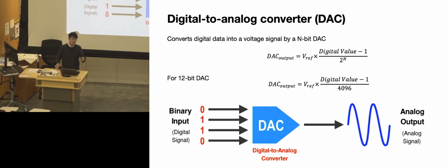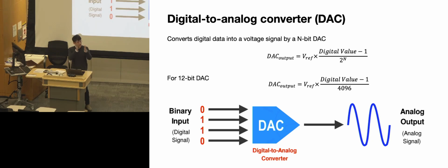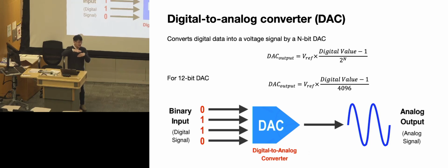That's a very good question. You could configure it as either everything run down, run up, or in the middle. I'm not sure if you remember in the last lecture, you could decide whether the 0 starts at 0 volt or starts at, say, the least significant bit, one step up. The essential reason for the -1 is that we have, say, n values, and there are only n minus 1 steps in between. So you can decide whether you want to shift it up a little bit or shift it down. It's essentially your own configuration. Usually people just push everything down.